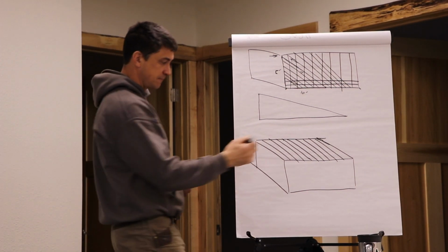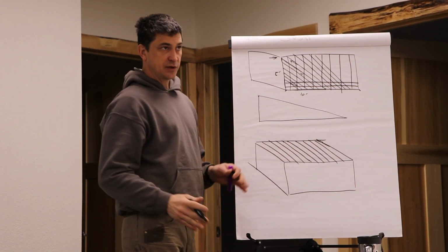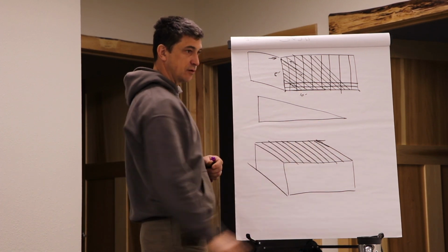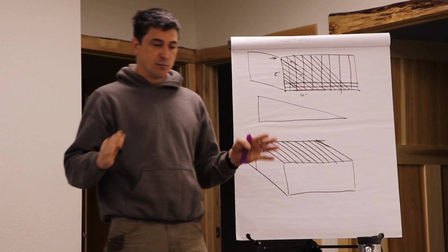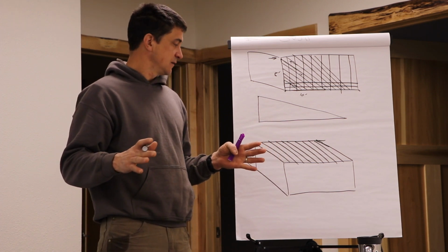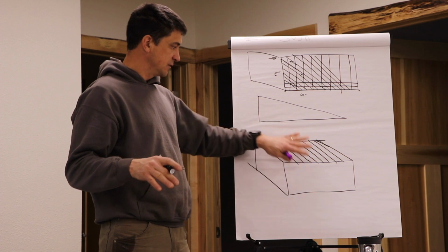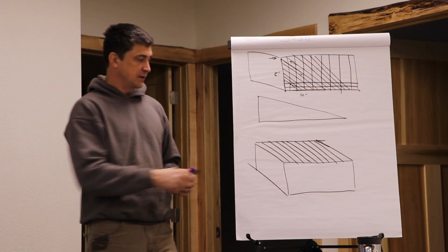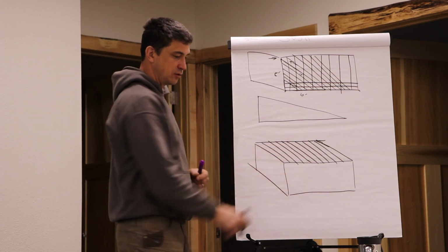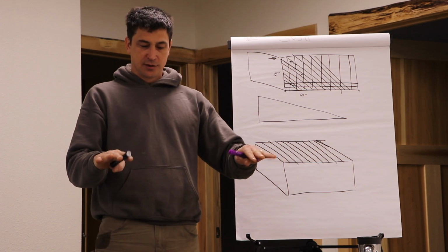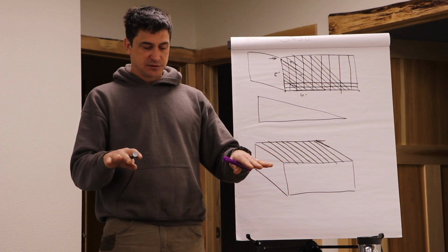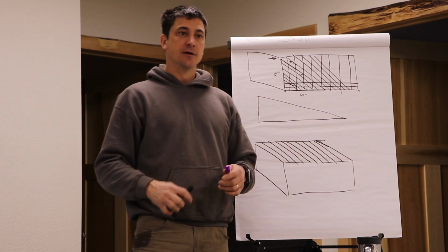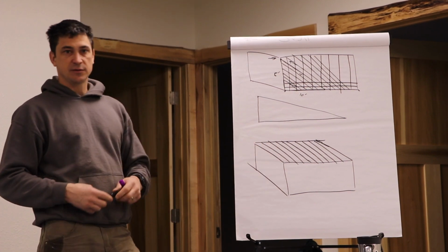So the same thing with the floor. The reason you'll see almost every single old house will have diagonal sheathing on the floor, because the most important brace system in an older home is the floor diaphragm. Okay? Diagonally sheathing the floor in the old days would lock that floor like this solid piece, and so the only way it could move was for the whole house to either twist or slide or whatever. And so it makes it extremely stiff.